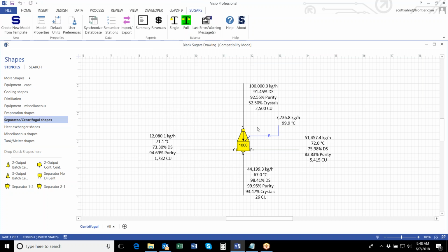So in this case, it's utilizing the original wash ratios and green and high wash ratios that came from the factory data, as if no one's adjusting this centrifugal. We're just leaving it alone, and we're letting whatever changes in the massecuite occur affect the sugar by whatever effect they may have. Does that make sense? Is everyone clear on that?